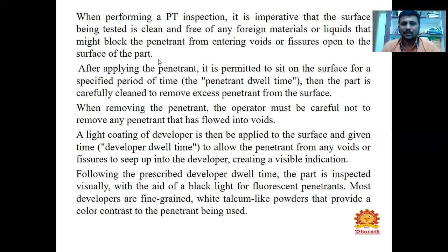Then the part is carefully cleaned to remove the excess penetrant from the surface. When removing the penetrant, the operator must be careful not to remove any penetrant that has flowed into the voids. If you remove the penetrant from the voids, what will happen? We cannot find the correct size and measurement of the cracks, gaps or defects. So we need to remove the excess penetrant, but the operator must be careful not to remove any penetrant that has flowed into the voids.